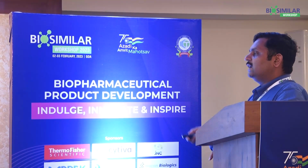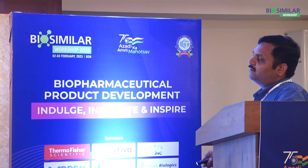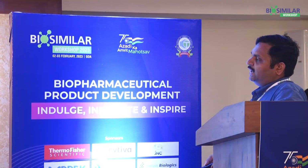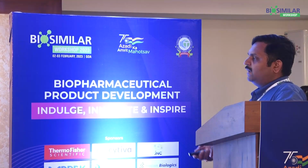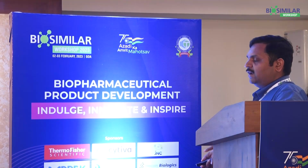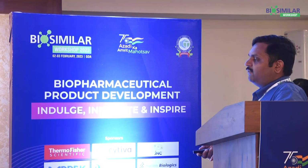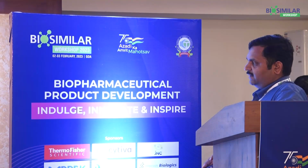Firstly, some initial experiments are required, like breakthrough curves of 3 different RTs or feed concentrations. Along with that, we definitely need some information about the resins, like column length, bead particles, particle porosity, then linear velocity and adsorption parameters. Along with that, mass transfer parameters are also required, which can be derived from the breakthrough curves which were generated. And we are going to talk about these in upcoming slides.